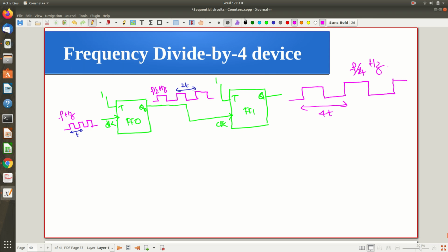for you. So this is a diagram, and now I am going to explore what a clock is. I will take some clock signal. This is what I am planning, and then I will see what my Q0 is, then I will see what my Q1 is, and you will get this Q0 as something like this, 2 times the input period, and Q1 will be something like this also. This is what I want to verify.